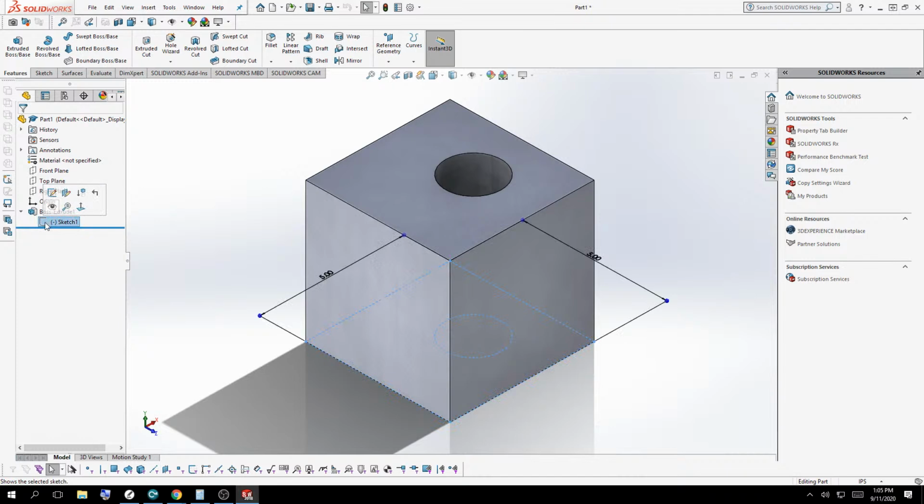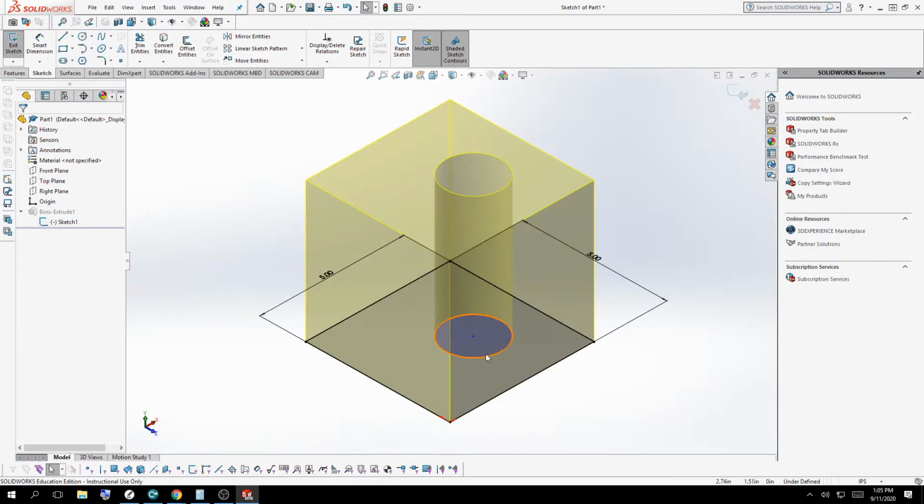We're going to click the icon of the sketch, not the word. If you click the word, what's going to happen is most students end up clicking on this, and then all of a sudden it goes to renaming your sketch. So that's confusing. But to avoid all of that, you're going to click the little icon of the sketch, upper left corner of the Edit Sketch button, and that's how you can get in.